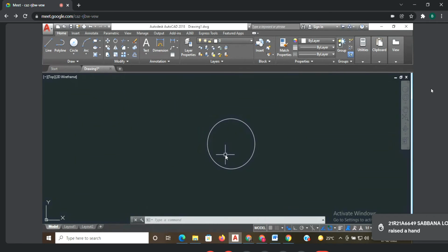Nothing but these are your limits. That's why first you have to set the limits. In these limits, suppose I draw a circle of 50 mm, it won't give any change. Directly, if it is 50 mm radius, I will get the circle. It won't be a smaller circle, it won't be a larger circle. Exact size you will get on the screen. Definitely you have to do these three steps initially when you start the system. First is units, then limits, next zoom out.